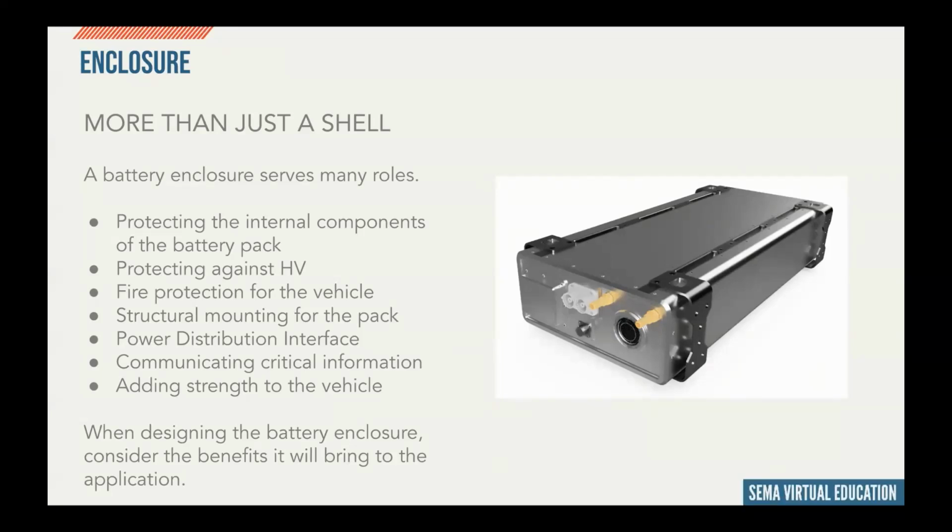So the enclosure is meant to protect the internal components, as well as protecting externally against access to high voltage, to keep high voltage and all the current contained within the pack and the energy stored within the pack safely. A proper enclosure can provide fire protection for the vehicle in case of a thermal runaway or any type of fire or impact. They provide a way to structurally mount the pack safely within a vehicle platform, and an interface for all the power distribution, cooling lines, and sometimes even features that show state of charge.